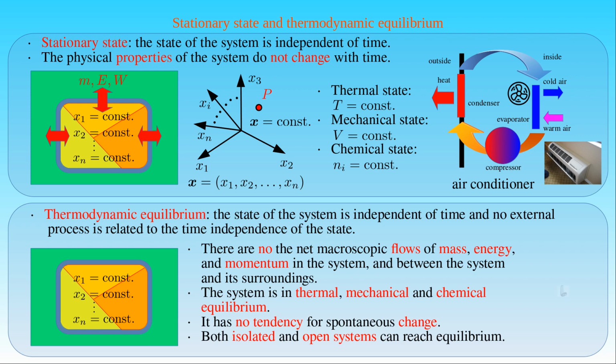These two cases can be demonstrated with a Dewar flask or thermos. If we fill the flask with any substance at a given temperature and close it, then its impermeable and adiabatic fixed wall will prevent any transport between the substance in the flask and the environment. As a result, the substance is in equilibrium and remains in the same state until we remove the cap of the flask. Then the substance can exchange heat with its surroundings and mix with it, depending on whether it is a gas or fluid. After equalizing its temperature with that of the surroundings, the substance will reach its equilibrium in the open flask.